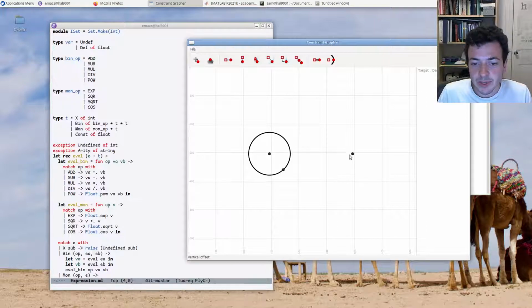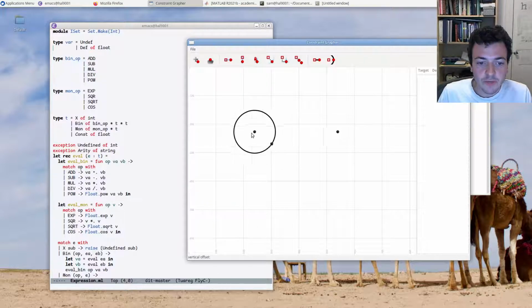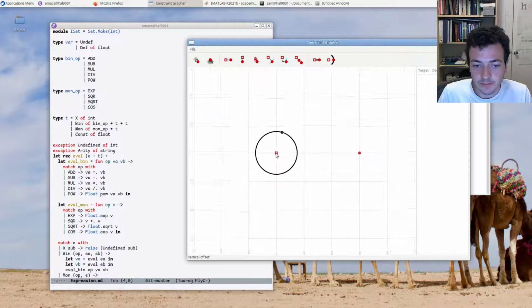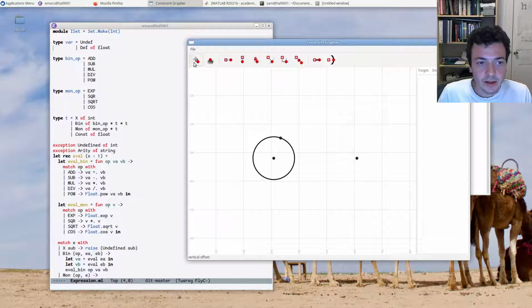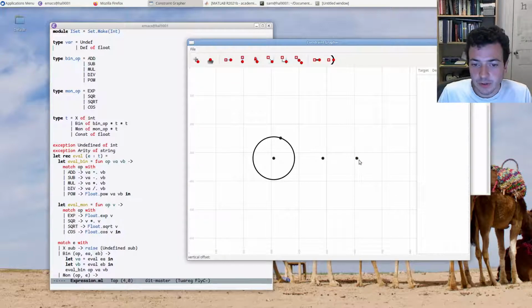So now this point is locked in place, but just as a demonstration, if I remove this lock constraint, I can move the entire system, but this point and this point remain relatively locked to each other. So I'll go ahead and add that back. And now we need a point to move back and forth as the wheel rotates. So I'll place that point there and constrain it to always be horizontal with our point here. And now we can move this point along like this.